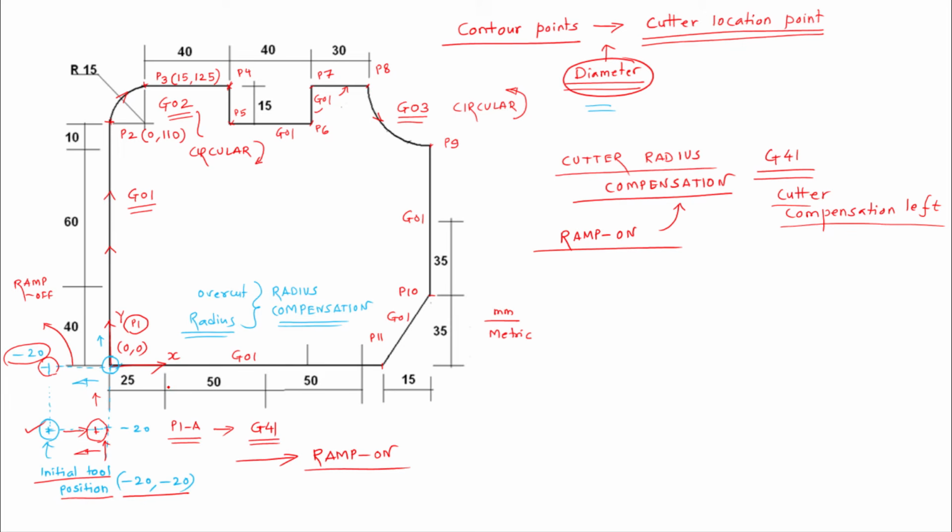Along the x direction, it is the air distance with the given feed, but that will ensure the perfect corner at the P1 point. So the ramp off will ensure the safe exit of the cutting tool and the better accuracy or the exact machining of the corner. So in this way, the ramp on and ramp off are to be considered along with the cutter compensation methodology.